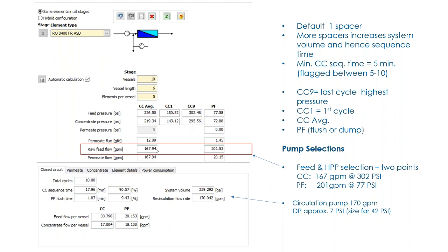So in general, if you select in the middle of the curve at the most efficient point, you have lots of room to go 20% or 1.2 over, especially since it's at significantly lower pressure.